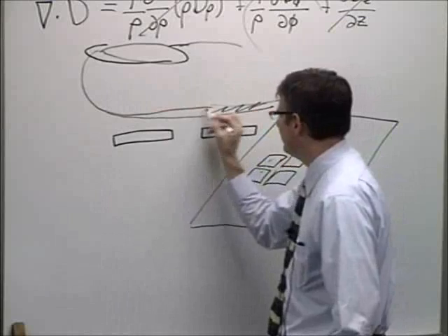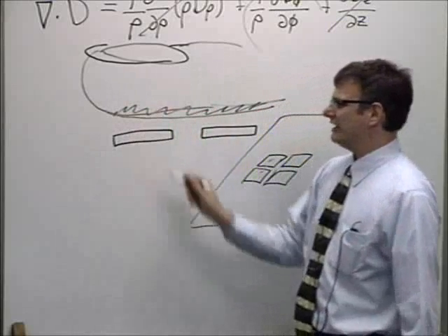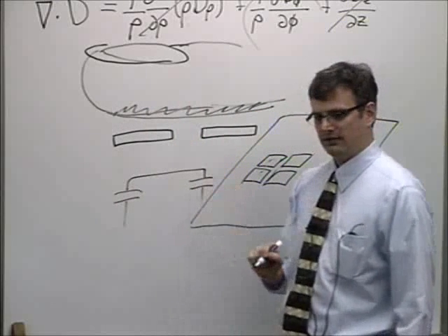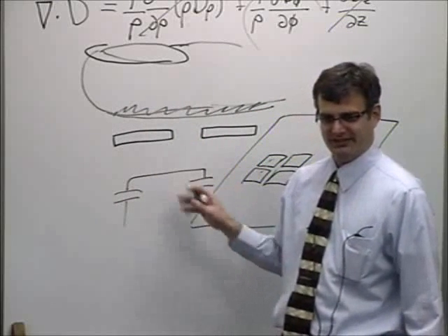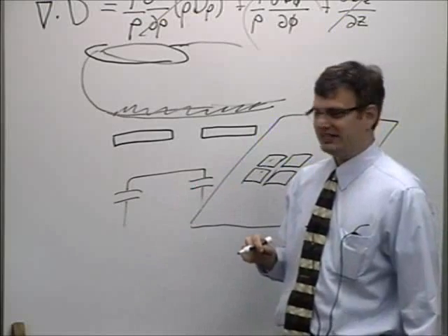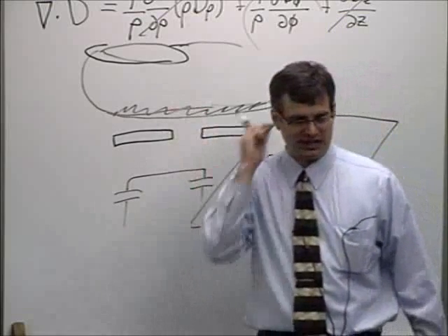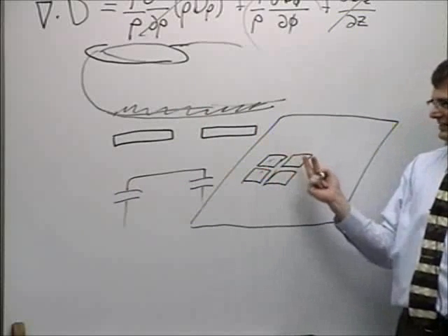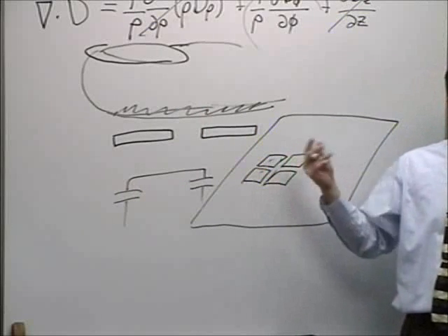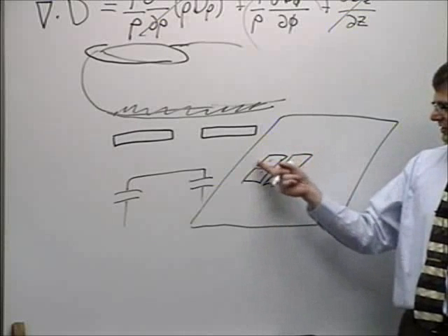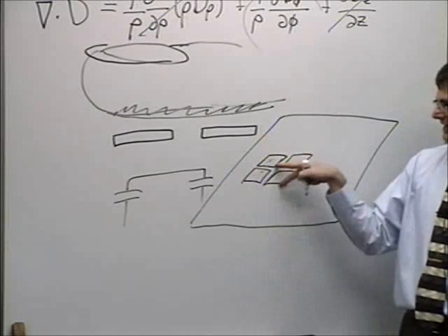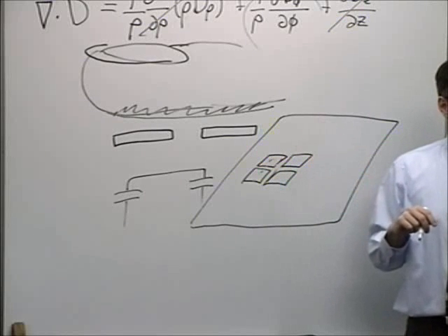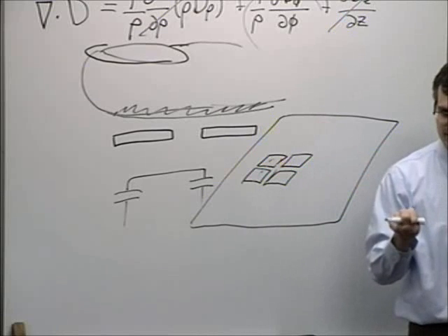It's a conductive finger. And now it's like two parallel plate capacitors in series. We could calculate that too if we wanted to. That's easy. So you can see that you change the configuration, you change the capacitance in that area. And by selectively analyzing with test currents and an A to D sampler on a microcontroller, you can pull out the instantaneous capacitance between any pair of capacitors on the screen and sense, is that finger getting close? Is it moving away?